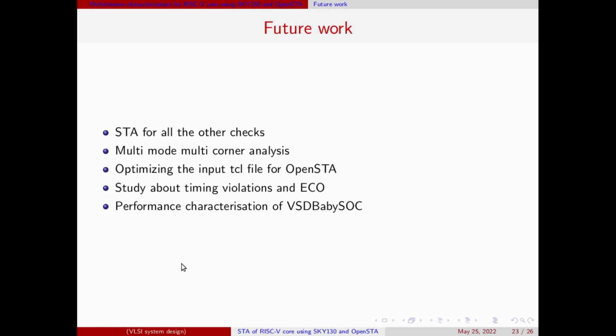And then for future work, in my analysis I basically stuck to the basic reg to reg analysis, and there are different other checks which need to be done. I will be doing the STA for all other checks, and then the multi-mode multi-corner analysis, as I had used the same library.